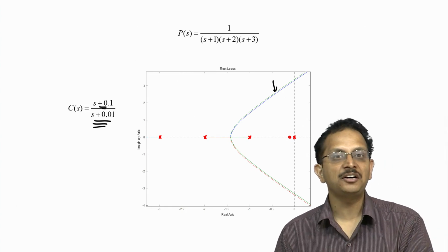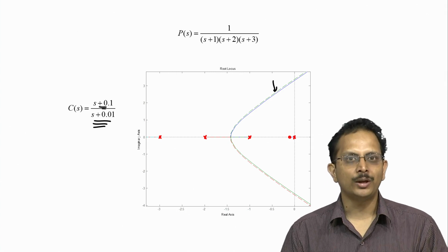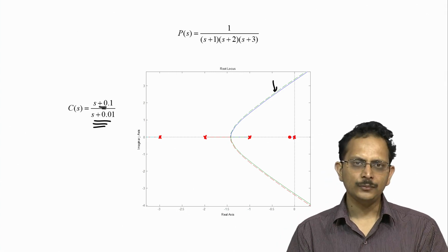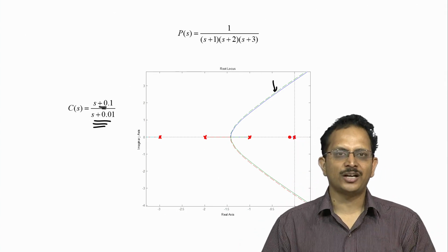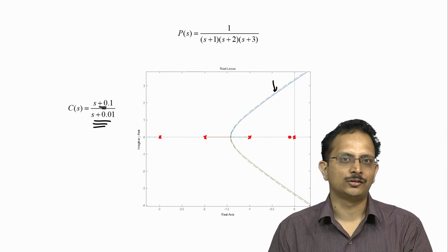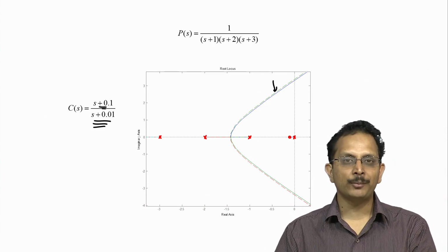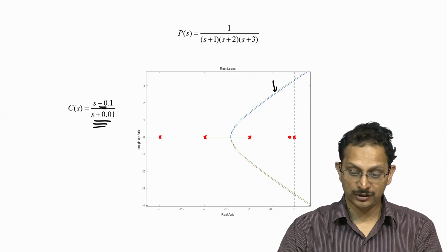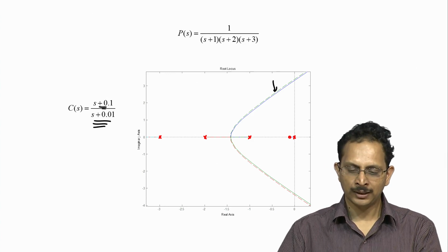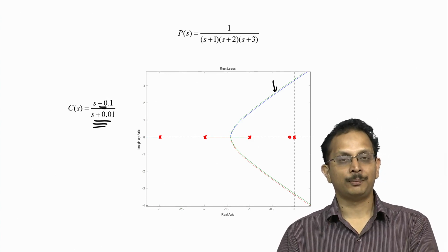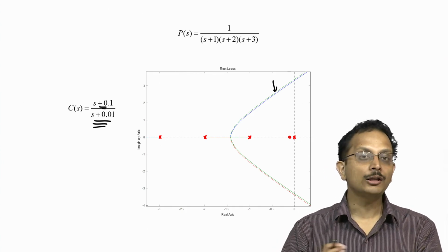is not as powerful a tool as Bode plots when we are performing control design, but still it is a very useful complementary tool to analyze the overall response of control systems once we are done with the design of a controller. So, although one might not always want to use root locus as the tool of choice for performing control design, owing to the difficulties associated with satisfying performance specifications, even though stability specifications are very easy to satisfy because we know exactly where the closed loop poles are going to be located, the root locus still performs a very valuable service by allowing us to check where all the closed loop poles of our system are.